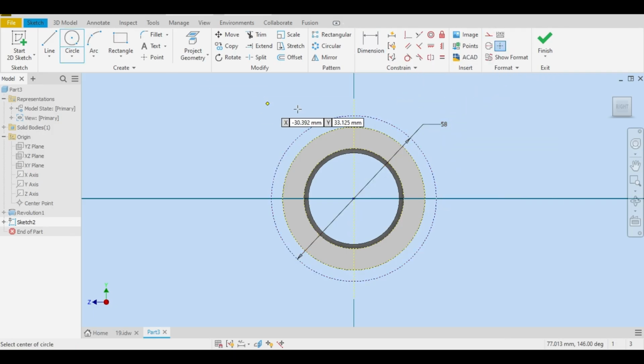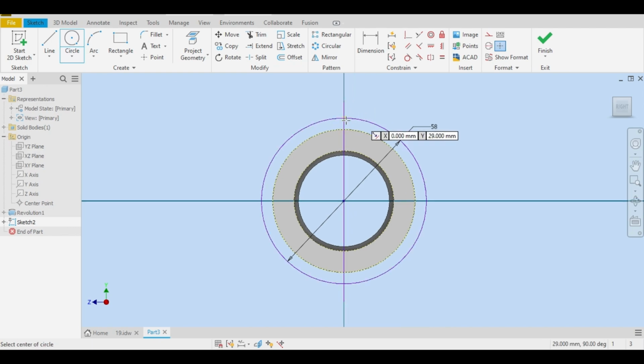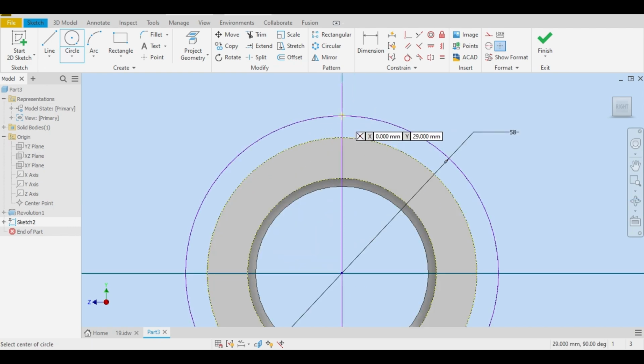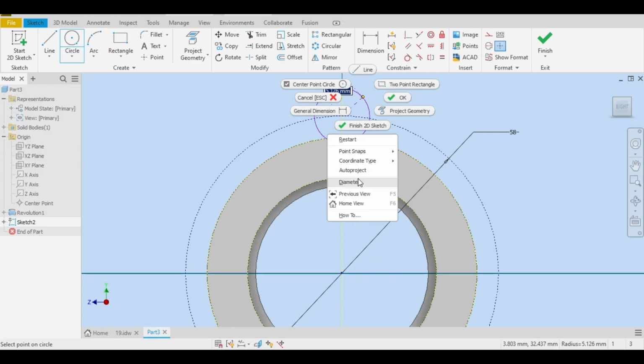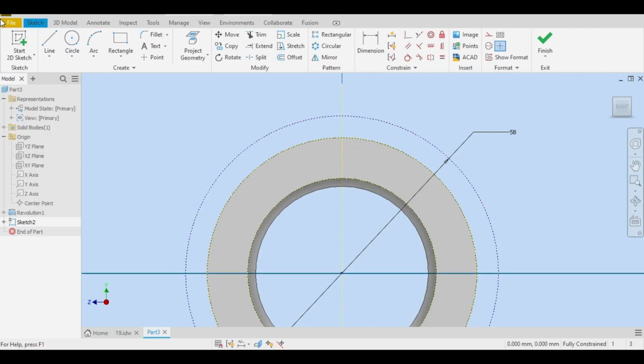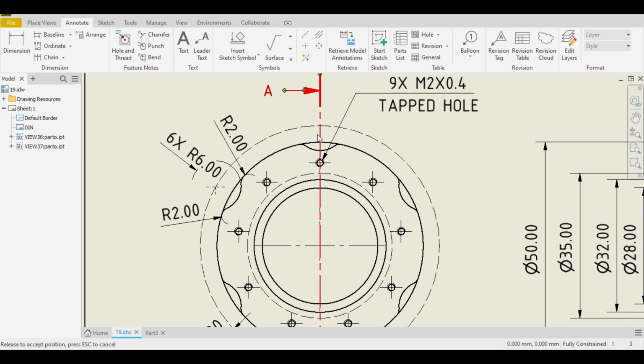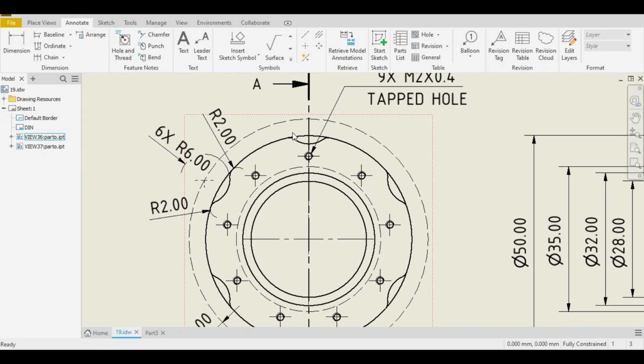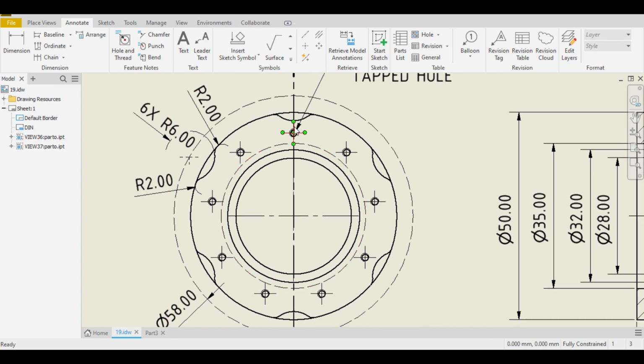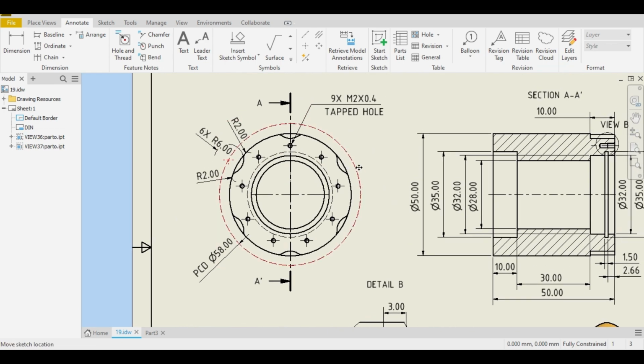Okay, now we will draw an arc, a radius circle like this. Let me type, okay, it is radius. Let me select again. At this point it is radius, not diameter. So it was 6, I guess. Let me go back to the sheet and see. Okay, radius 6. It is at the center of this line. So I just simply made this so we can later use a circular pattern for this feature.